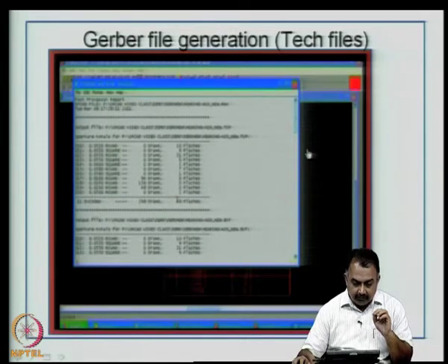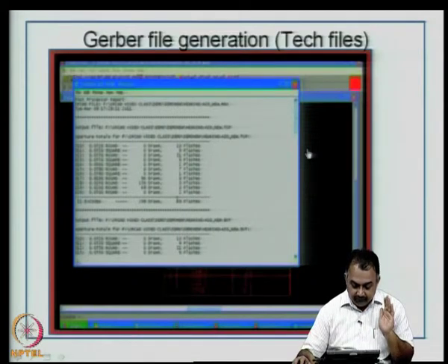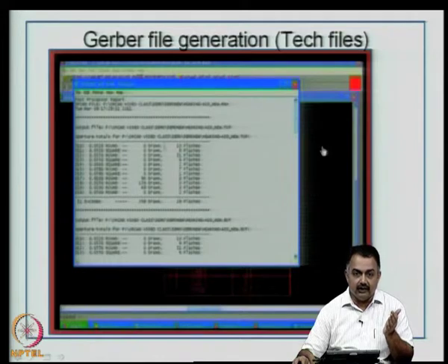It talks about the pad sizes, the track sizes. This is known as D codes. Okay. So, the D codes are universal and is accepted by all Gerber based photo plotting machines across the globe. So, you can send this set of information anywhere and get your masks done.